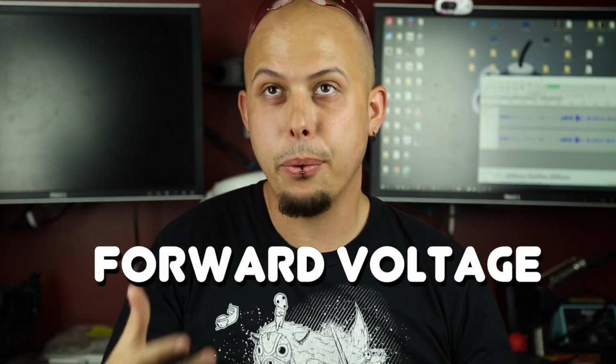In the world of diodes, we have to consider something called forward voltage. What that really means to us when we're planning out our circuit is that there's a certain threshold of voltage that needs to be reached before it will allow any electricity to go through the device.